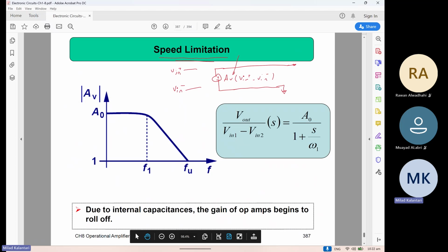No matter if the frequency is very low or very high, it has the same gain value. But in practice, it is not possible to generate this very broadband high gain. In practice, every circuit has some limits, and the gain will start dropping.